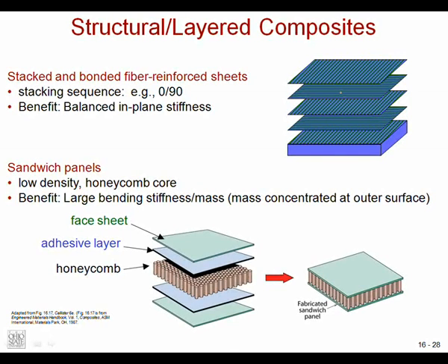Now, sandwich panels, this is another interesting thing. So why do we use these? What's really great about sandwich panels? What mechanical property do you like them for? They're low density. They're very stiff, right? If you think about using this, you'd use it in something where it might be a bending load. They're very stiff. They're very resistant to bending. And so what's great about these is the density is all concentrated on the outside. And we just have this here with a honeycomb structure.